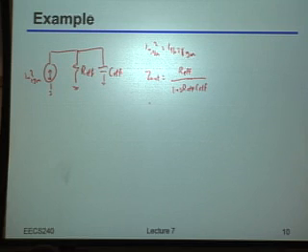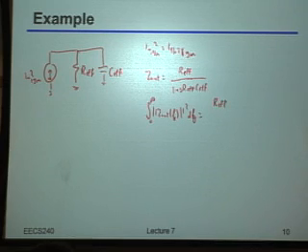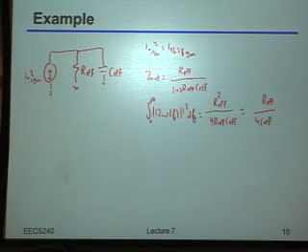As a reminder, if we were to integrate that output impedance versus frequency, remember, to get things in my standard form, you usually pull the numerator out in front, and then you know the integration for the denominator. That's just going to be R effective squared over 4 R effective C effective, which of course is just equal to R effective over 4 C effective.